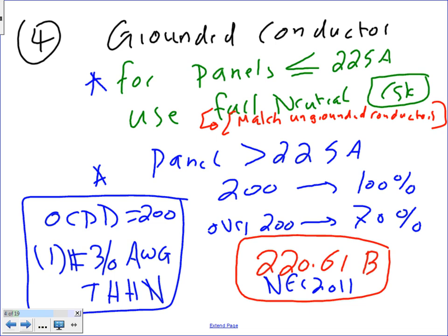Any question about this? That's a piece of cake, huh? So I have 4 conductors, 3/0 each. Okay, number 4. Any question about number 4? That's a neutral. If you don't have a neutral, then you don't have to do this calculation. But we have a lighting panel. That's typical, like what you guys are doing in a project. Our lighting panel is 200 amp. That's exactly what you guys are going to have for your panel.